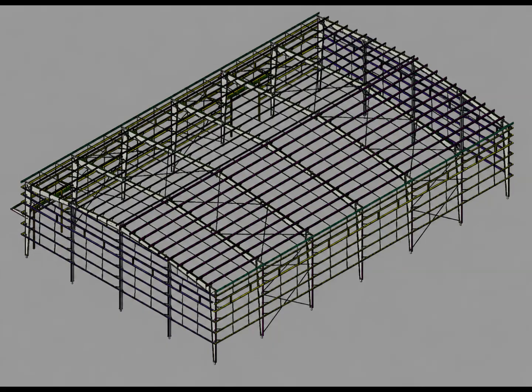Now pay attention to the diagonal members. These are the bracing components. In the side wall, the diagonal members form braced bays. This is something we studied in detail throughout our previous videos. We looked at side wall X-bracing, roof X-bracing, bracing connections, and the connection of bracing members to structural members. Here, instead of looking at only one bracing bay, we can see how the bracing is incorporated into the complete building.